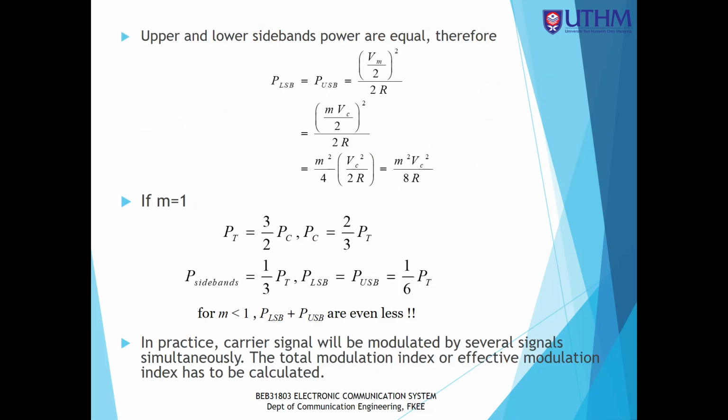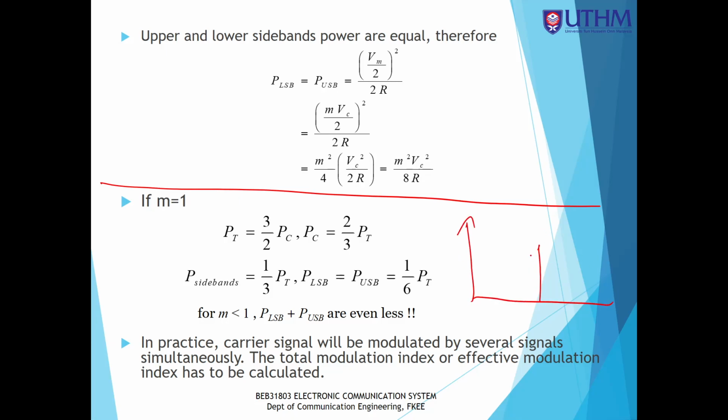Okay, so we have learned that even during the ideal case, the carrier component consumes 2/3 of the total power. 2/3 of the total power belongs to the carrier.